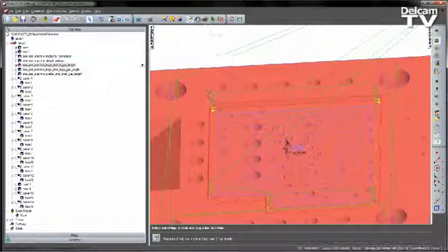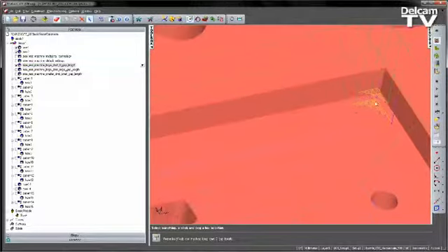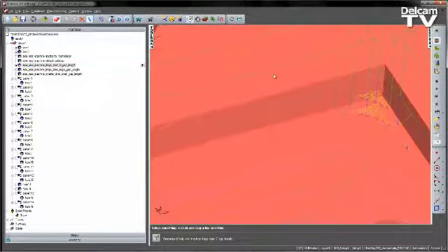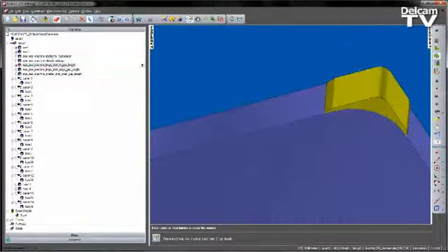Now if I come in and do the finishing operations, you can see we've only finished those corner regions as well. So using a detect material thicker than value that is too large, we'll end up not machining the areas that we want to machine. And we can verify this with a 3D simulation. If we play this through, you can see we're left with material around the outside of the component.